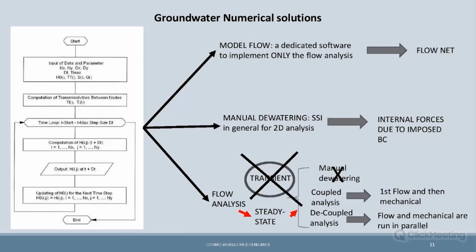Within the steady state, we have also three options. At least MIDAS is offering us three options. In particular, MIDAS in this case is similar to Plaxis. So in Plaxis we can do it. In FLAC we cannot; in FLAC we hardly have these two. Okay, the manual dewatering does not have to be used, because if we are in steady state, doing manual dewatering is mixing apples with oranges. So if we want to carry out manual dewatering, it's better to do, I would say, classical stress analysis.